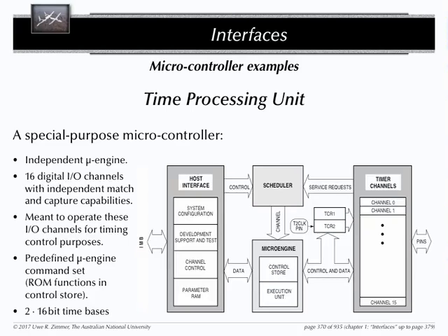Things where timing is really important, where you don't want it being interrupted, or you just want it to do one task and stay doing that. Mm-hmm. It's one of the many options to use concurrency to address hard real-time constraints. Because if you use concurrency in a clever way, then you can decouple completely from your mainstream. This is a pretty extreme form of decoupling because you remember how they are communicating with the main CPU. They use dual-ported RAMs, which is a quite beautiful way of interacting in a real-time fashion.